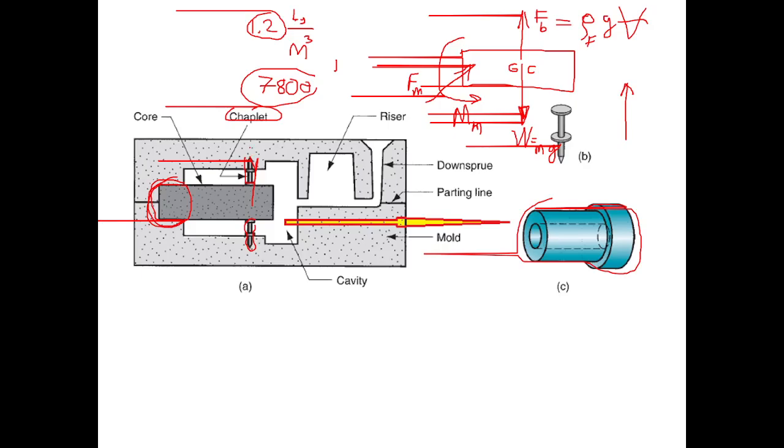It is to apply a force. For instance, the chaplet is over here, and that is the force applied by the chaplet, F sub chaplet C. Then, draw the free body diagram and be able to find the magnitude of the force it is to apply by the chaplet.